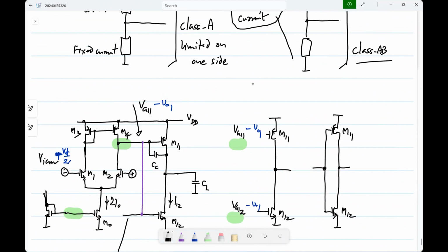No, both are the same, right? And then let's say you bias them in the saturation region, or you self-bias this. Self-bias meaning you connect the input and output. What will be the operating point current? It will depend on the supply voltage, actually quite strongly. This is like going back to constant VGS biasing, right?